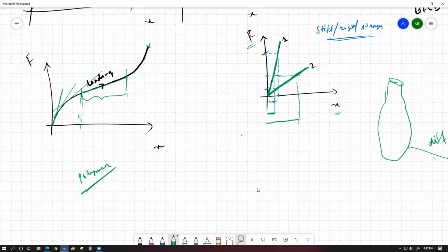And there is almost no definitive straight line within the curve. Although this part pretty much looks like a straight line, if we actually take graph points of polymerized substances, there is no part of the graph that we can definitively say to be a straight line. This is why polymerized substances have no defined Young's modulus.